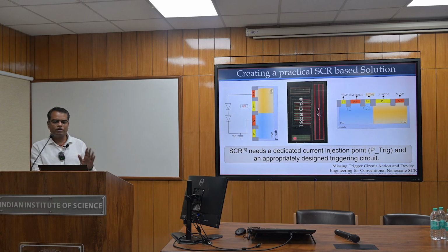Okay, so with this brief background, let me also cover why creating a practical SCR-based solution is very difficult. In order to trigger it earlier than the avalanche breakdown voltage, we need to create a trigger circuit, or use other circuit techniques to lower the trigger voltage of an SCR.